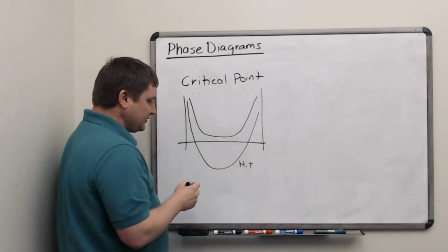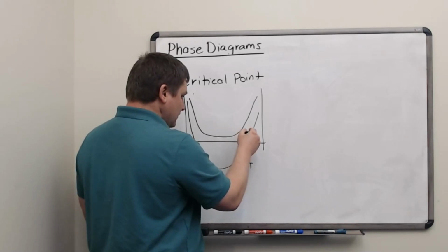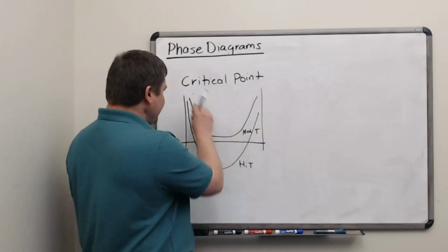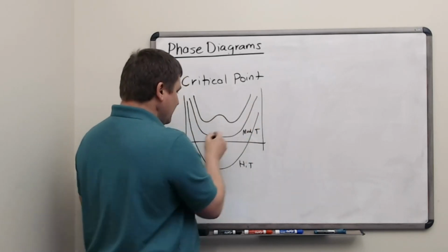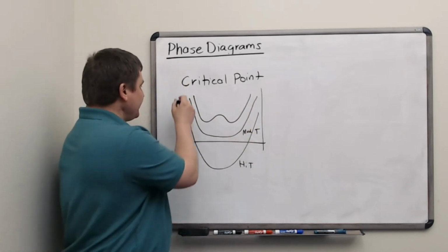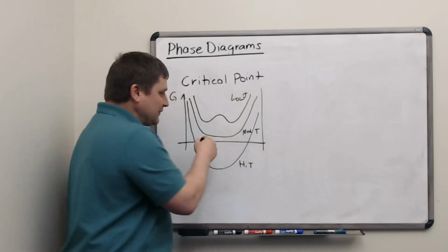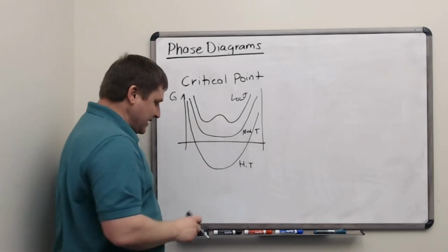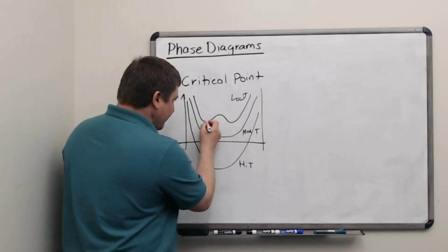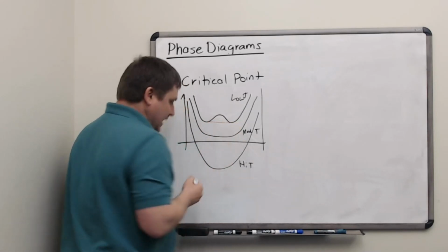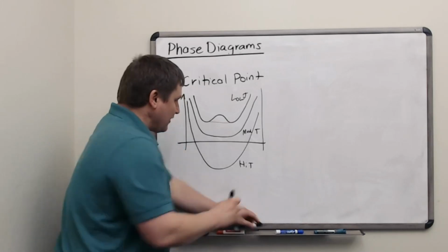So at a high temperature, we have no concavity. At a medium temperature, we begin to generate some flatter region on the Gibbs free energy curve. At a low temperature, the Gibbs free energy curve may naturally develop a concavity. And when that happens, the concavity is bridged by a convex hull line, and that becomes a phase separation mixture region.